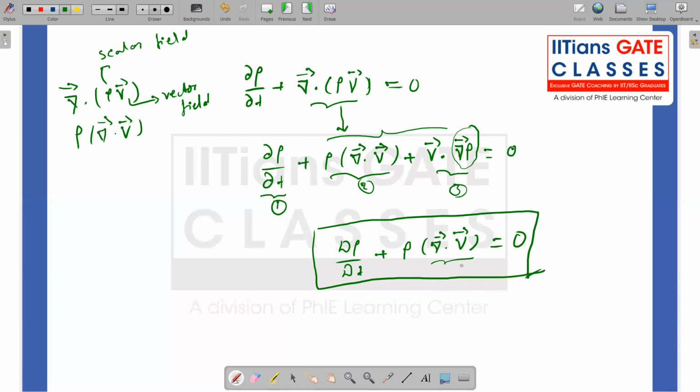All we have to satisfy is that the velocity vector is divergence free, or I can write the velocity vector as a gradient of some potential. If I can write that, I can use the potential equations even for a compressible flow. What this indicates is that in a potential flow my velocity vector is conservative. But that is just for thought.